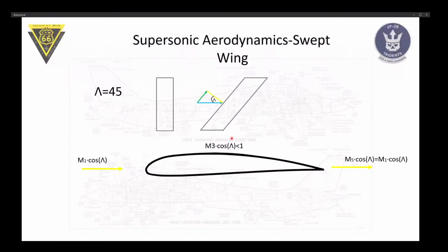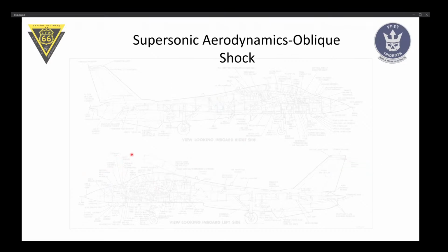number. The critical Mach number is the Mach number at which this wave drag starts to rise, and the phenomenon is called drag divergence. So this is basically why we're using wing sweep. By angling the wings backwards, we reduce the effective speed, and this wave drag gets pushed back towards higher Mach numbers. So this helps us fly faster, really. Yeah, exactly. It's below Mach critical.